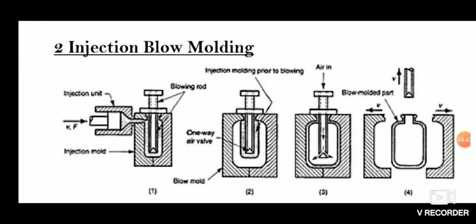The injection blow molding machine is based on the extruder barrel and screw assembly, which melts the polymer. The molten polymer is fed into a hot runner manifold where it is injected through the nozzles onto a heated cavity and core pin.